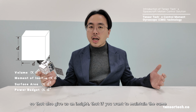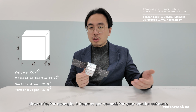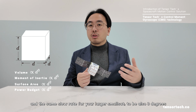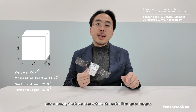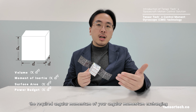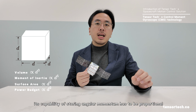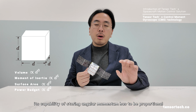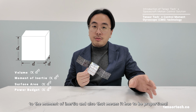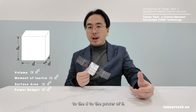That also gives us an insight that if you want to maintain the same slew rate, for example 3 degrees per second, for your smaller CubeSats and also for your larger small sats, then when the satellite gets larger, the required angular momentum storing capability of your angular momentum exchanging devices, like reaction wheels or CMGs, has to be proportional to the moment of inertia, and also proportional to d to the power of 5.